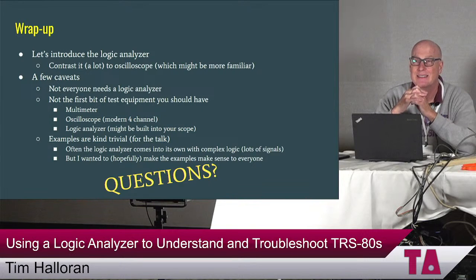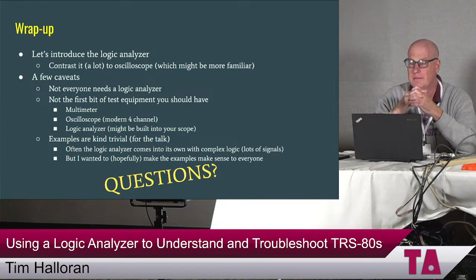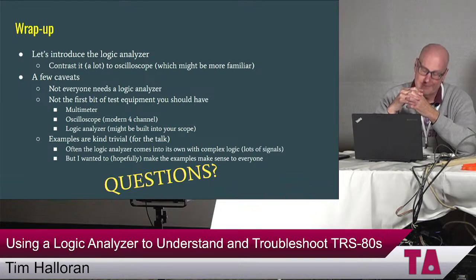I'd say start at the HP 16.7Xs and move up. The 60s, they're not fast. The 70s, they're about 2 nanoseconds, so 500 MHz. That's pretty fast. And those actually have a lot of extra things such as state analysis. You can go up to 132 channels on a logic analyzer at a time. They're very capable machines.